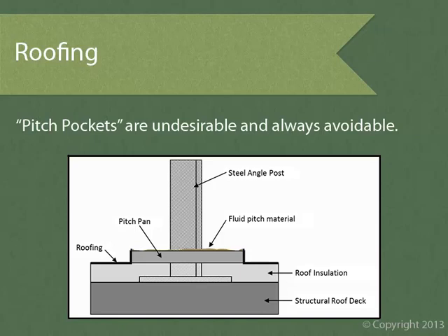Use steel pipe and tube steel shapes in lieu of angles, wide flange shapes, C-channels, unistrut, or other steel members for which a roof jack cannot attain a proper seal. Conduits and pipes should penetrate the roof individually, not in groupings. We'll actually talk about MEP penetrations a little bit later in this course.